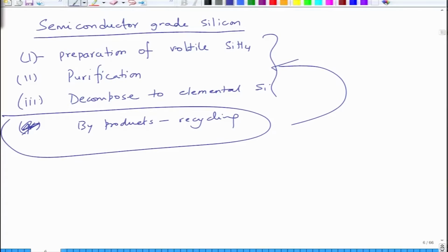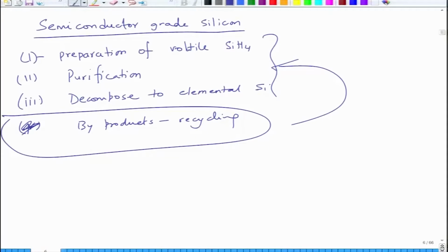So essentially you first make metallurgical grade silicon, then convert it into silicon compounds like silicon hydride, because remember, no matter how much liquid processing you do, you can't make very pure silicon. So, you have to take it to the vapor stage where only silicon is able to come out, the rest does not. So, after you have done primary refining using the metallurgy processes, you have to go to processes which are more deposition processes than liquid based processes. In this case there are three processes that we generally use, but generally the Siemens process is the one.